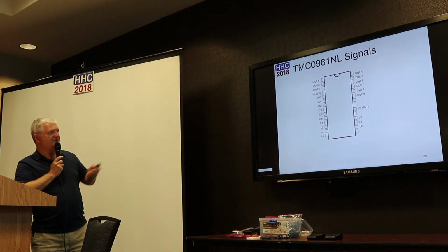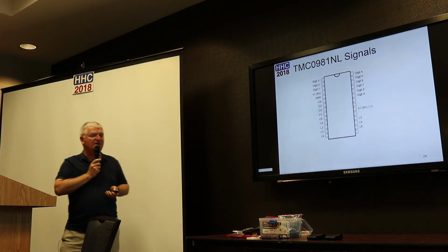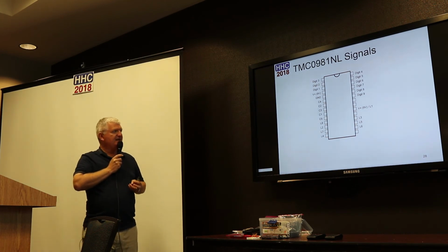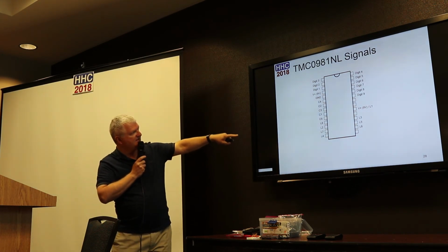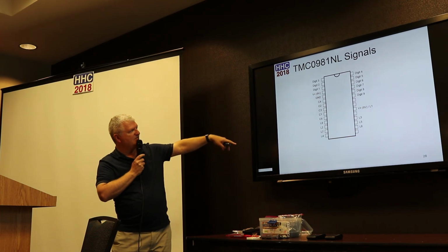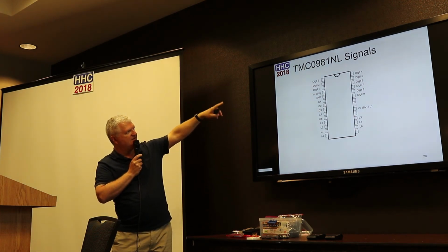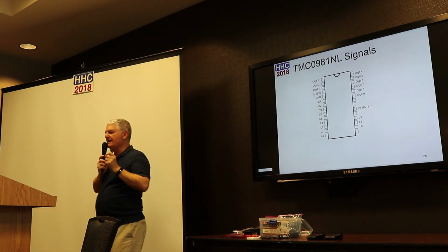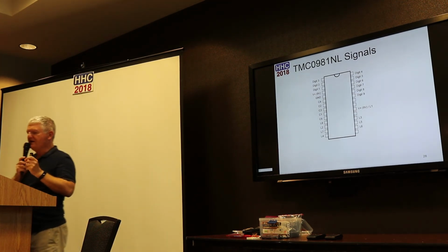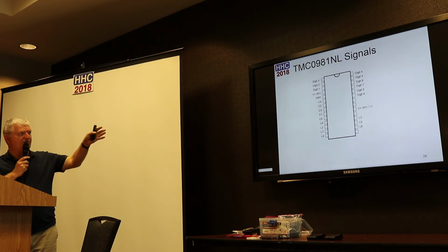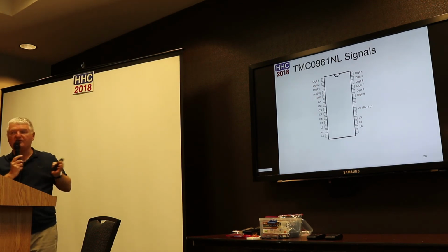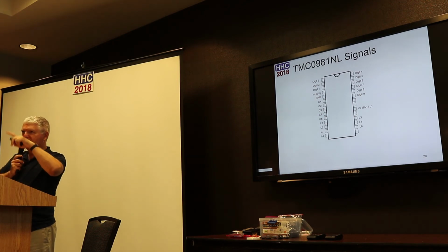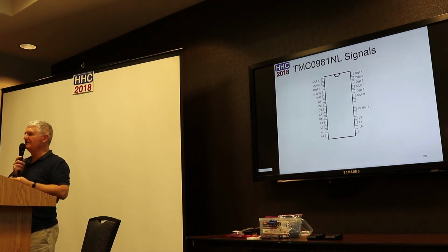The only thing I did is try to find out where the signals went and try to guess how that works. And I have two conclusions. Firstly, the L and C lines are addressing the keyboard, and digits are addressed by these up there, 1, 2, 3, up to 9. There are some missing lines, and actually there are not enough lines to address all the segments of an 8-segment display.